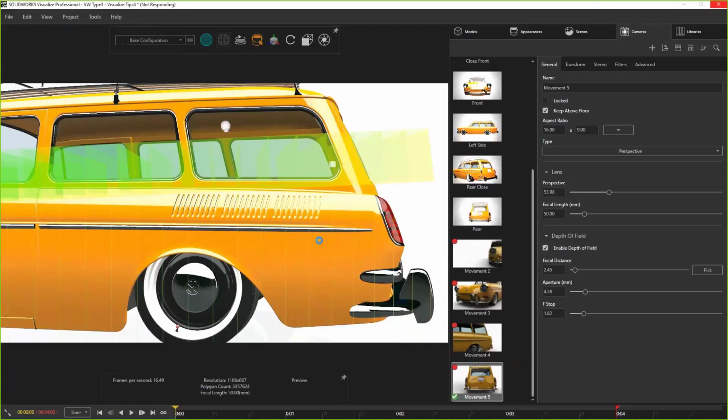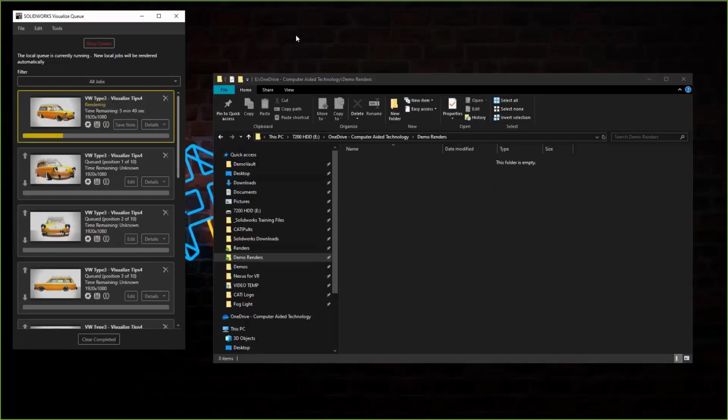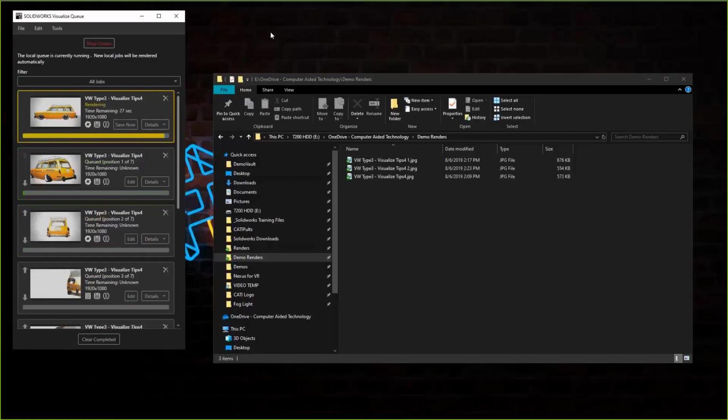And I wanted to show you guys about how long this stuff takes to render. So remember, these images we're rendering about 300 passes. On my machine, which is about a 4 gigahertz machine, those renderings at 1080p are taking about 6 to 7 minutes to complete each one of those images. And they're pretty complex in terms of post-processing. We've got some focal effects going on. So that's a pretty good render time. 5 minutes is pretty quick, especially for a fully 1080p image.